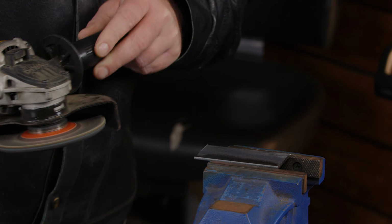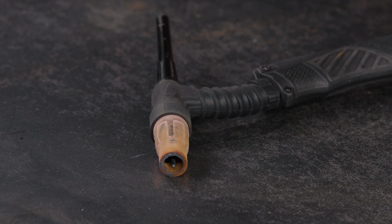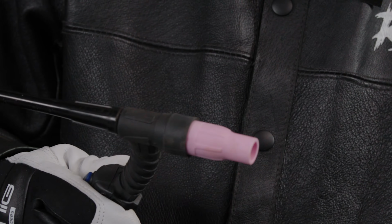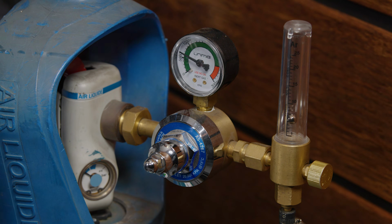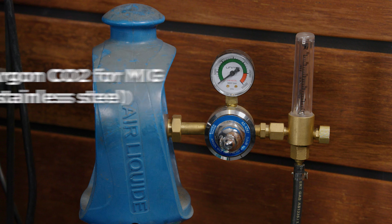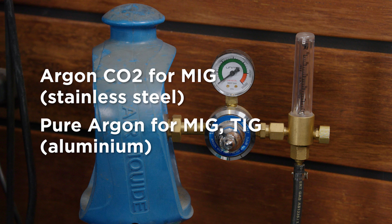So how can you prevent it or fix it? Thoroughly clean your parent metal and give your filler a wipe down. Clean your consumables and replace any that are worn or damaged. Also make sure your equipment is moisture free. Check out your gas flow on MIG or TIG. Unimig recommends 8 to 12 litres a minute, and also make sure it's not leaking or empty. Check you have the correct type of gas: Argon CO2 for MIG, stainless and steel, pure argon for MIG aluminium and TIG.